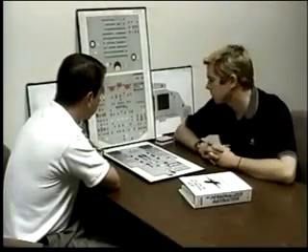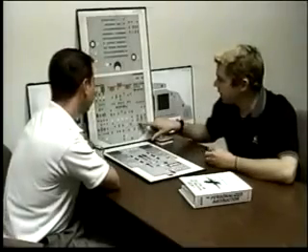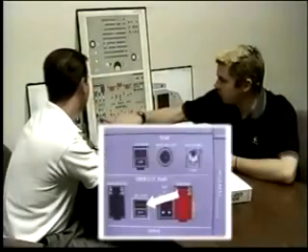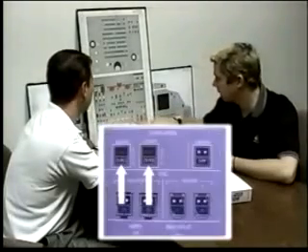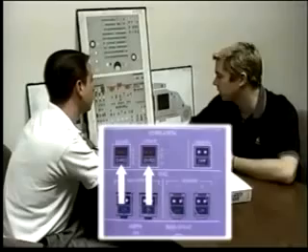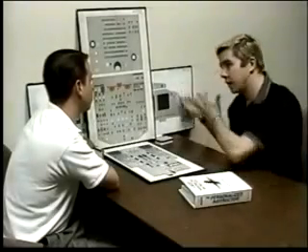What about the scenario of taking both to override, and when would you might do that? Well, to do that, I'm more than likely, I've got a smoke light over in the Gen 1 line switch. And by selecting these both to override, I'm going to the smoke configuration. I'm still introducing air-conditioned air to the system, but I'm basically venting it overboard.